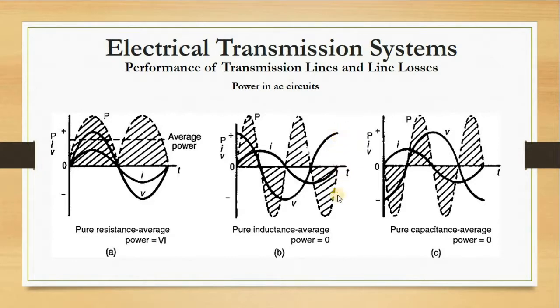And since the inductor reacts to change in current, and the current is changing from 0 to 2 amps, the inductor is going to react to that change. In other words, if it were just a resistor, we would say it's going to resist it. It's going to oppose that change. So whilst it is reacting to the change in current, it is already seeing the voltage.